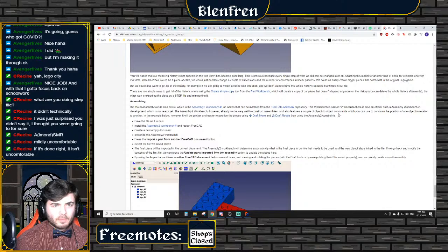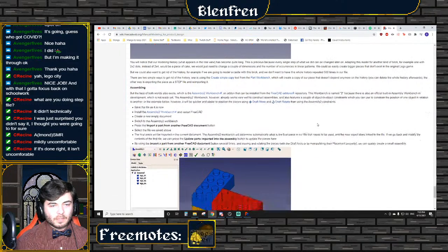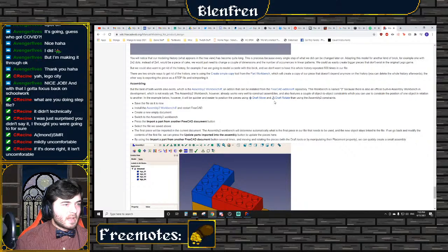And also features a couple of object-to-object constraints, which you can use to constrain the position of one object in relation to another. In the example below, however, it'd be quicker and easier to position the pieces using draft move and draft rotate than using assembly 2 constraints. Save it as it is now. Install the...